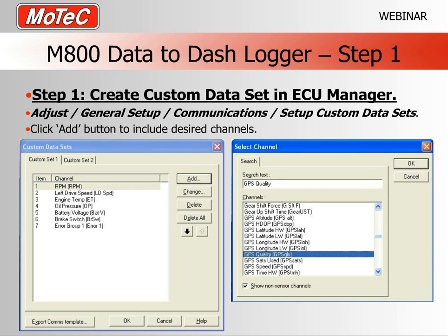And what you will then see on your screen is the box on the left-hand side that I'm showing now. Custom data sets. As you can see, there are 2 custom data sets that you may configure. We'll just look at one of them for the moment. Now, what we're looking at here is a custom data set that's already been set up for an application. But if you were to open this in, let's say, a blank configuration, you would simply have an empty list there. So what you then need to do is click on the Add button, which is the one I've just highlighted, and that will then open up a second table, which you can see here.